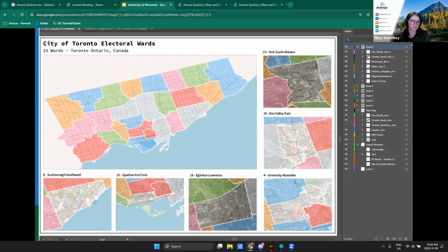My recommendation is to not shy away from the use of non-map layers for organization here. It will save you a ton of time. If something goes wrong, you can easily target your layers. You know where to find them. The MAPublisher tools will always pull your layer from the map views panel, where they're each independent, in their respective map views. So nesting it in a non-map layer has no impact. So I highly recommend you consider keeping things organized in your documents.